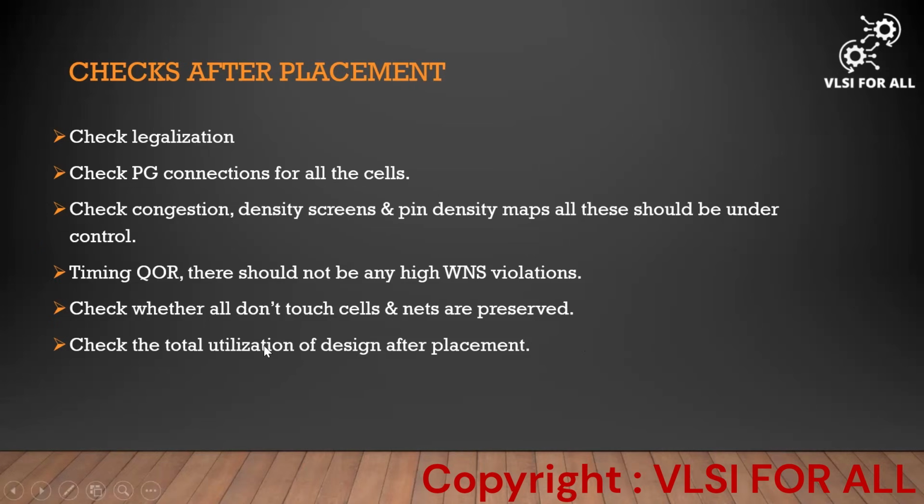And next, check the total utilization of the design after placement. So once placement is done, we have to check the utilization. This is a major factor, because if utilization is high, then going to further stages it will be more complex and very difficult to resolve those issues. So as much as possible, we should improve the utilization in the placement stage only. In one situation I faced, the utilization number was high. After checking, I came to know that register optimization had been disabled. After I enabled it, I got better utilization.